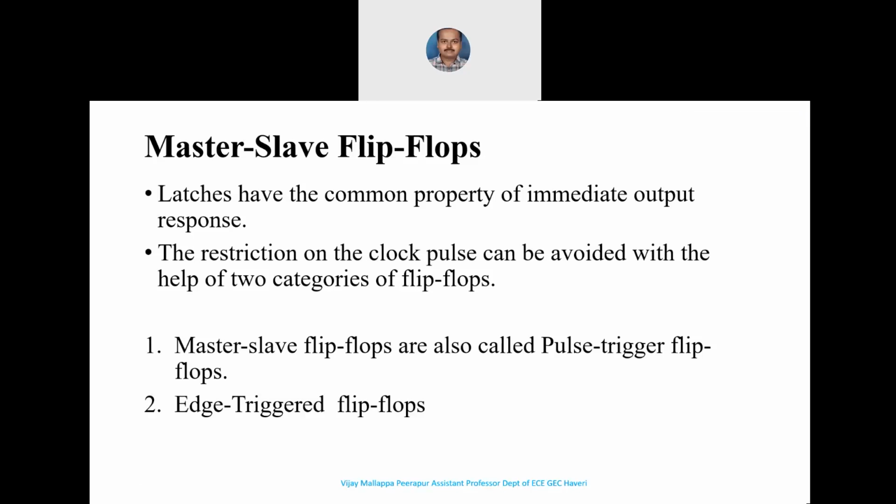I said that with latches, as and when you give the input, the output will be impacted immediately, depending on the enable signal, right? Also, I spoke about the drawback or limitation we have when flip-flops are dependent on the clock pulse. I explained one condition: when J and K inputs are equal to logic 1, and the clock input is 1. And we assume that the clock pulse is logic 1 for a long period of time.